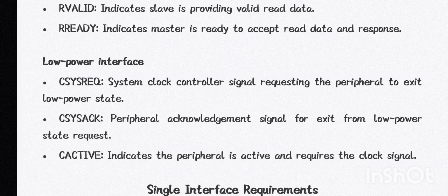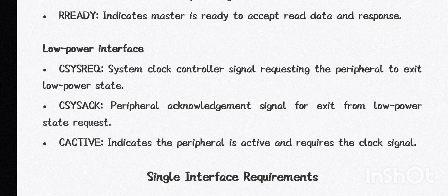Low power interface. CSYSREQ is the system clock controller signal requesting the peripheral to exit the low power state. CSYSACK is the peripheral acknowledgement signal for the exit from low power state request. CACTIVE indicates the peripheral is active and requires the clock signal.